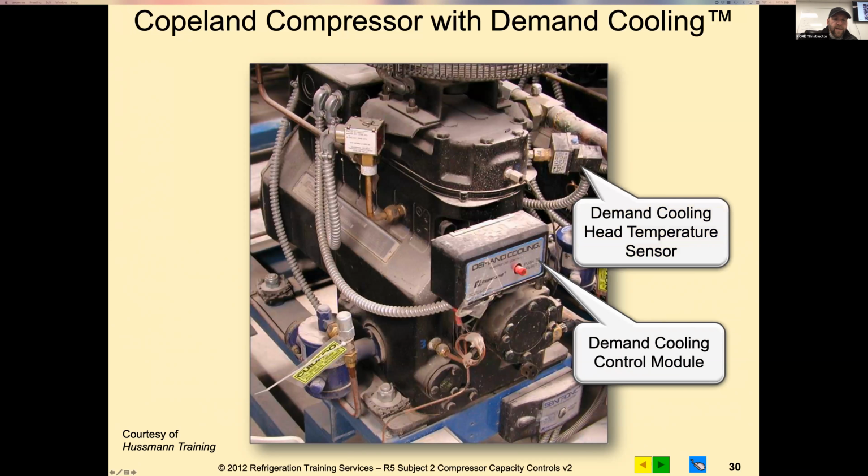So demand cooling head temperature sensors, that is not a head temperature sensor, by the way, guys. That's a flaw. That is a head pressure control with a manual reset.